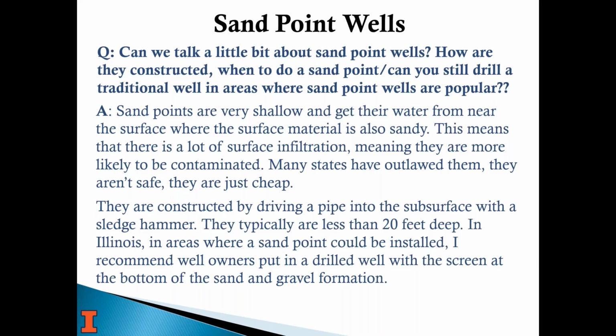Because there's so much water available in those types of aquifers, if the water table is only at 6 or 7 feet, you can use a sledgehammer and basically sledge in a screen and pipe, keeping the screen 5 feet on, metal pipe, 3-inch maybe or less in diameter, and in the end have a well that will provide enough water for your home. It's in a sandy area. Everything infiltrates into the ground. There's no grout around the well, so anything can get into your well from the surface. Most states, or many states, have outlawed sandpoint wells.